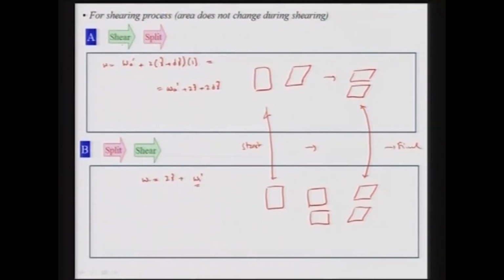So in this case also we can see the overall work which is being done by the surface shear stresses. That is again W1 minus W naught dash, given by 2 tau xy d epsilon xy. So what we can see here is 2 gamma plus 2 d gamma minus 2 gamma, which is equivalent to 2 tau xy d epsilon xy. So we can see that tau xy is equal to d gamma by d epsilon xy.